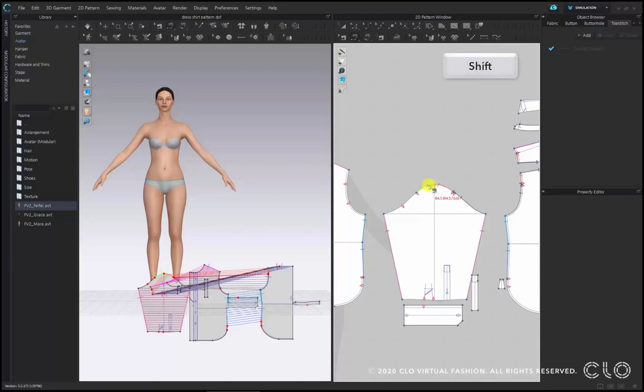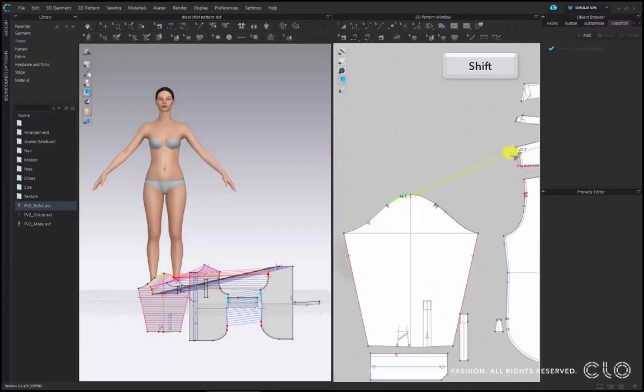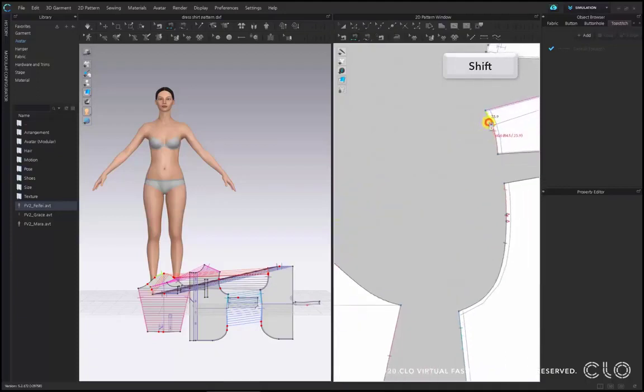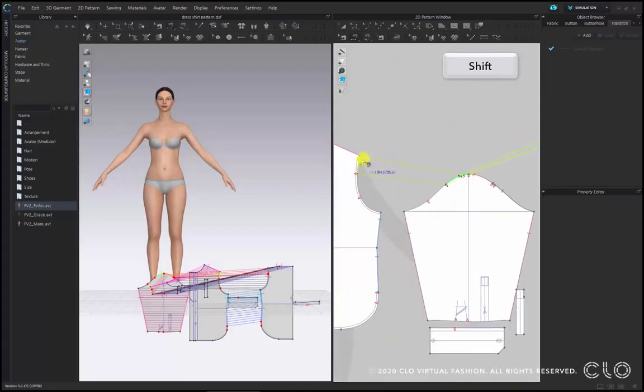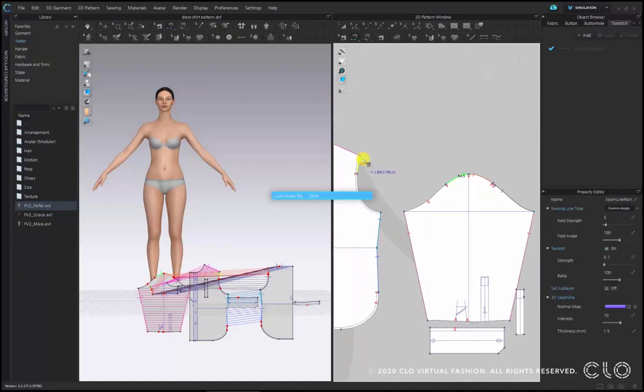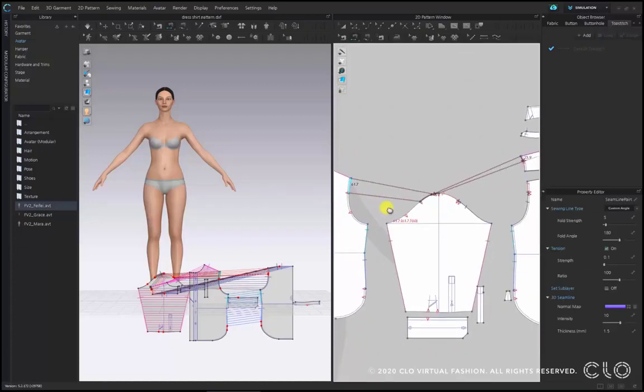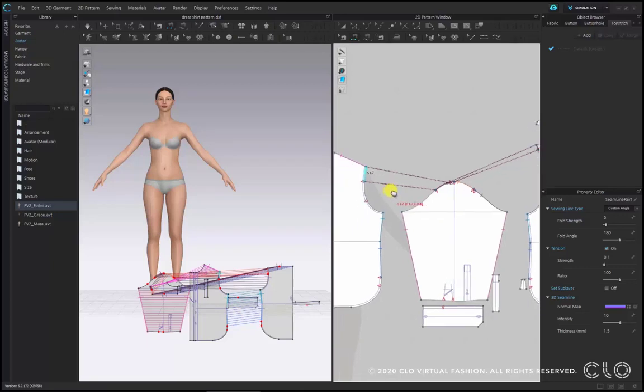Also, if you press the Shift key on the keyboard, the color of the sewing line will change to a fluorescent color. And then connect this sewing line with all corresponding ones on your armhole. Just in line with the sewing machine notch and make a connection as when sewing. If you let go of Shift, you can complete one or more sewing. In the case of many to many, you have to switch to the M to N sewing tool to work. In case of one to many, you don't have to change tools. Then the armhole is also aligned with the seam line. You can connect according to the notch.